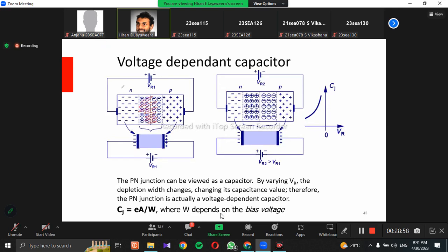So in this reverse bias mode, this region is basically an insulator. And this region is a conductor, and this region is also a very good conductor compared to this region. So then it's like a capacitor. The metal plates are here, and in this region you have an insulator. Now, applying a higher reverse voltage, you can move these plates towards the left. The insulation layer is increased.